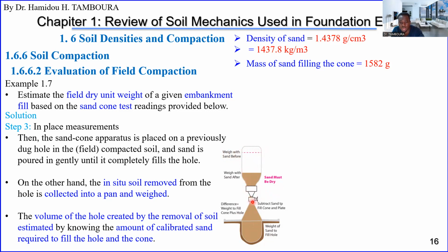And after opening and after filling the hole, but before filling the hole, of course, the sand will pass the cone, fill the hole, and fill the cone. Okay, and you go to weigh it again. After filling everything, you will remove the apparatus and go to weigh it. So the new weight will be, of course, less than the first one.